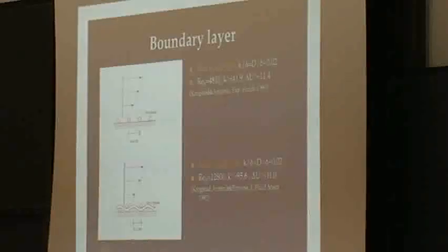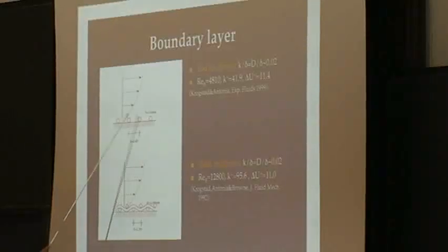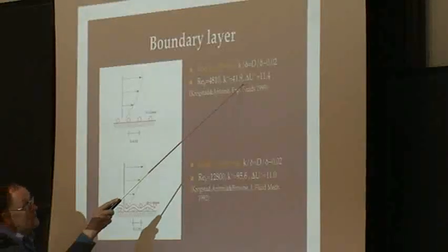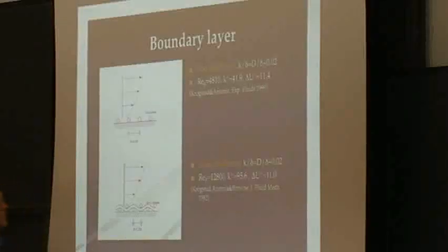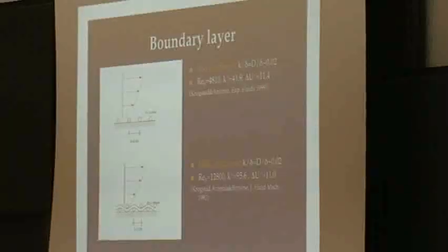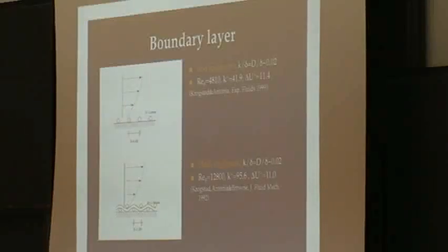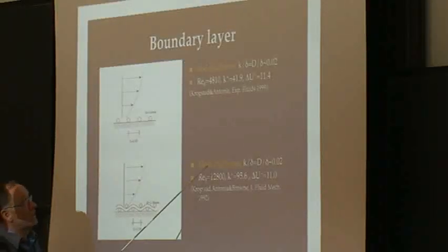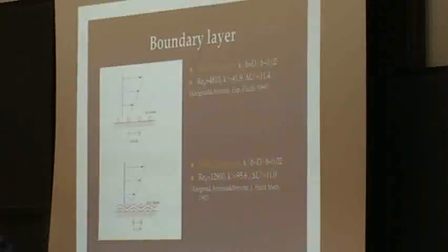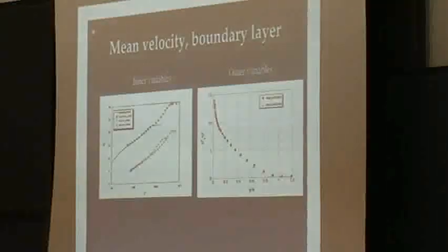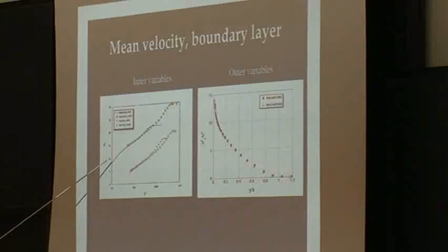outer layer. And we set this up so that the shift in the log law should be the same, which means that it should have the same effect on the mean flow in the two cases. But in order to do that, we needed to change the Reynolds number slightly. So this is changed by a factor of 2.5 roughly. But it's still high, so we think that there are very little Reynolds number effects. And here is the data.